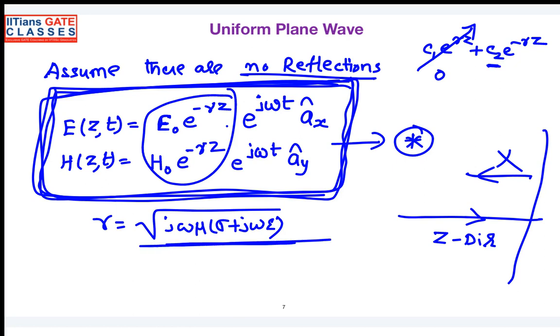Is conductivity negative or positive? Conductivity, permeability, and permittivity are all positive constants, right? Yes. So the propagation constant is always positive. If gamma is positive, what does this term represent then? Attenuation. Right. That matches your normal theory. When the wave is propagating in any medium, hardly can you expect there is no attenuation, or else the wave should attenuate. So there will not be any amplification.